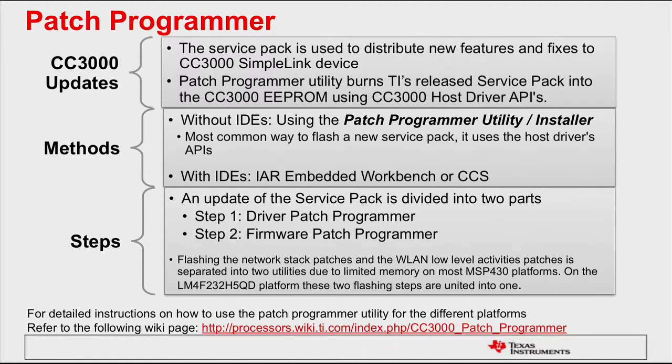There's also other methods through the IDE, either IAR or CCS, that you can download and bring the patch into the solution. So just from a high level perspective, there's a lot more information on the wiki and details about it. But if you're doing the patch programmer, it'll download in two steps. One is a driver patch, which is what you're putting onto the MCU itself. And then the other one is a firmware patch, which is actually going into the CC3000 solution.